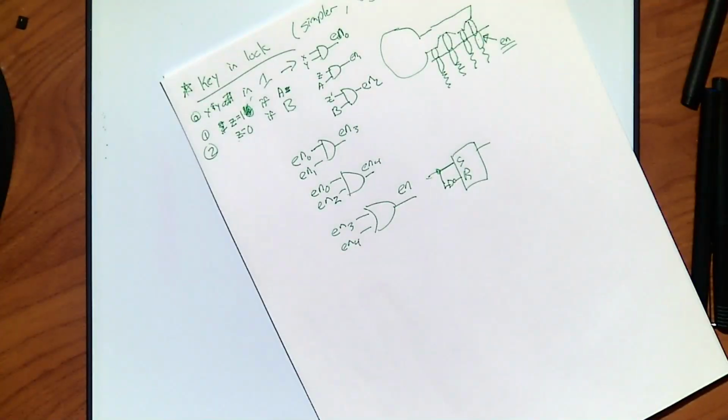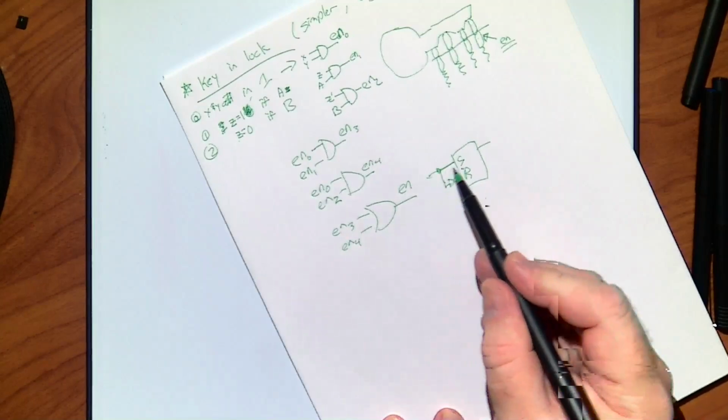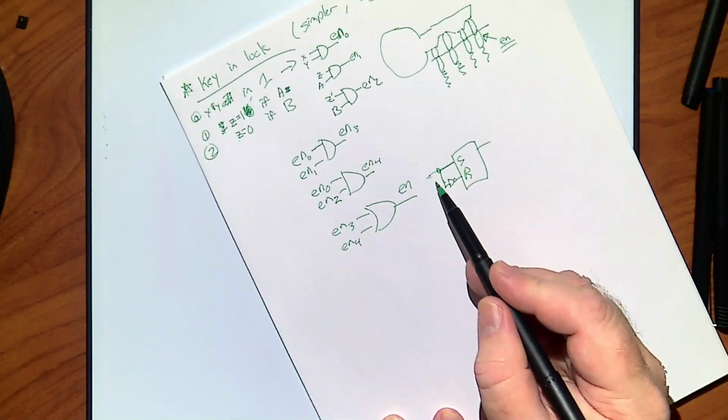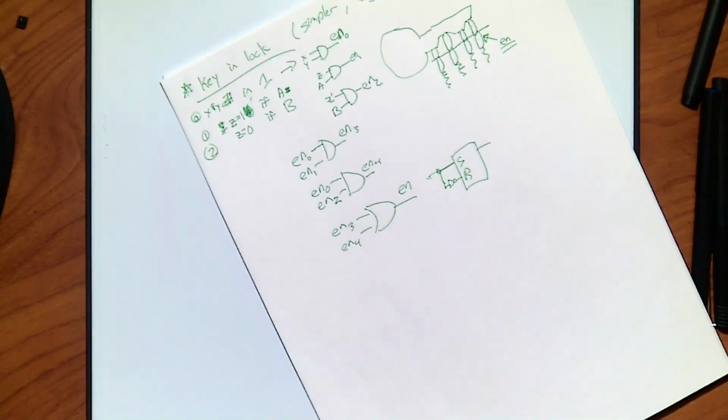That'll make a 1 go through. Right? If whatever's coming in is a 0, S gets a 0, it won't do anything. R gets a 1, so it'll reset, so it gets a 0. There's no way they can both be the same. I've made them the flip of each other. Right? So this is how you turn an SR into a D.